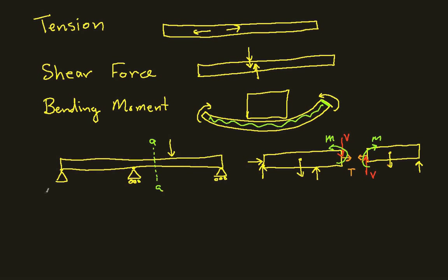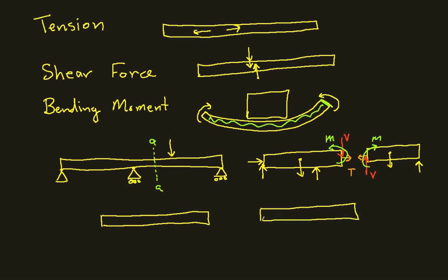When you talk about internal forces, you need to be a little careful. When we've talked in the past about free body diagrams, and we're assuming that we have completely rigid objects, we've talked about the idea that maybe gravity can be represented as just a force at the center of gravity of the object. But when you're looking for internal forces, you have to make very clear whether you have a concentrated force. So a concentrated force you might think of as an elephant wearing an ice skate standing on this beam. So the force, the weight of the elephant, is applied at pretty much exactly one point, versus a distributed force.